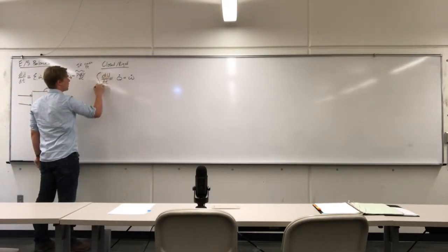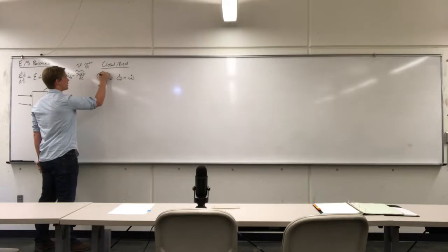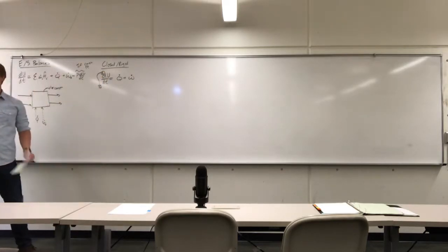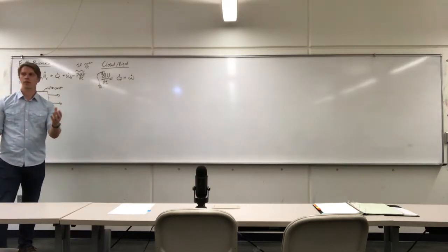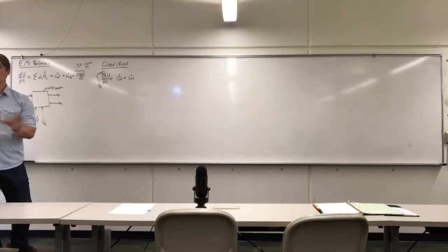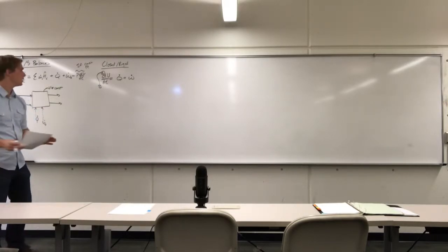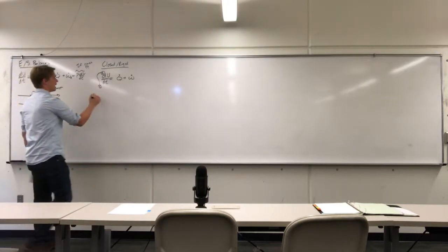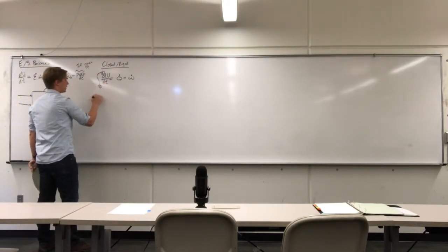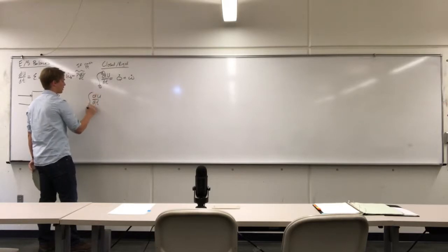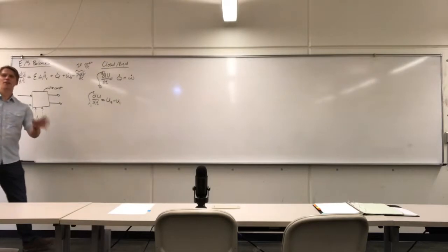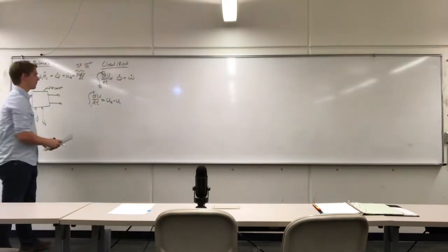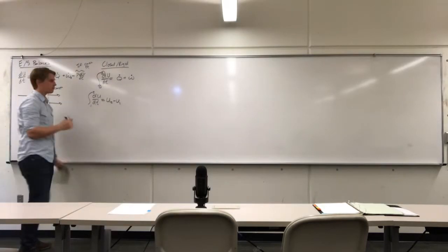What we would do is integrate this from state 1 to state 2. That's really the power of a state function in thermodynamics, we don't have to define how we're doing that. We know what the initial conditions are, we know what the final conditions are. And most generally, we want to set up all of our problems where we don't care about how it gets from point A to point B. We just know that it gets there. So this is the case then. If I integrate du, the change in internal energy, from state 1 to state 2, this is what it means. That's it. The calculus in thermodynamics is very fun. It's really easy. You integrate it, done.